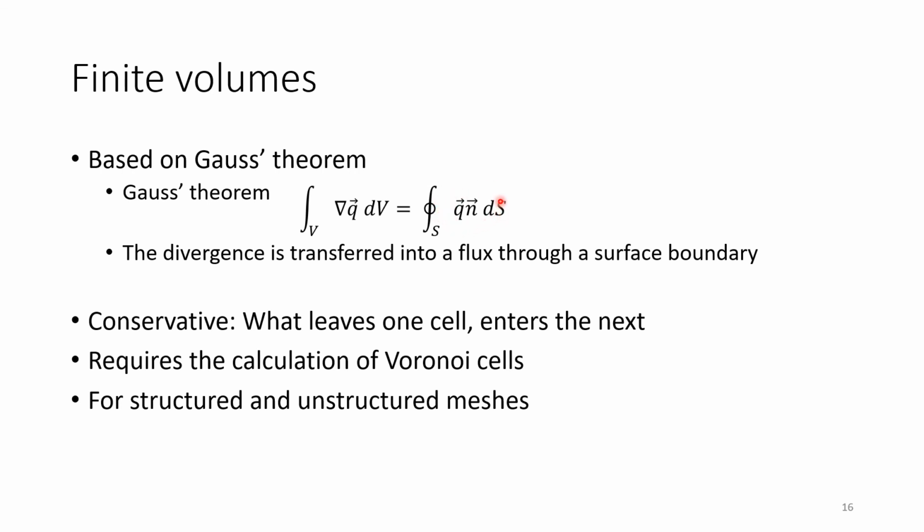And this is, for fluid dynamics, we have some mass moving from one volume to another, right? This is very close to what's actually happening in our mathematical concept. And that's why we call it mass conservative, because there can't be mass lost. Because everything that leaves one cell is automatically entering the neighboring cell. And with other methods, this is often not given. So there can be problems. That's what we discuss in a future lecture. Instability, inaccuracies, because they're not mass conserving. But finite volumes do this, and this is one of the strong benefits of it.